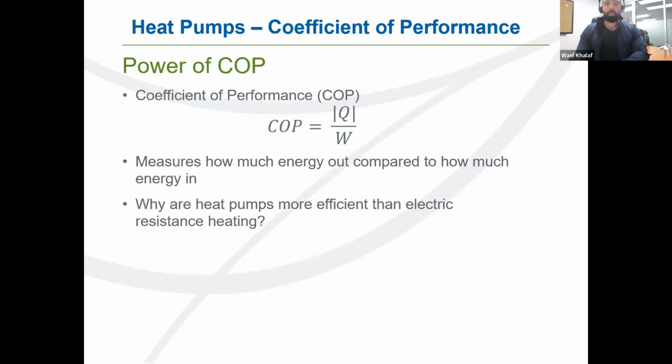So looking at this, one thing we should really dig deeper into is the efficiency of a heat pump. And it's really important to understand what drives the efficiency of the heat pump so we can understand where we want to make the decision or what parameters we want to make this decision for. So the COP value simply defines the thermal energy output of a heat pump versus how much electricity you have to put in for a particular period of time.